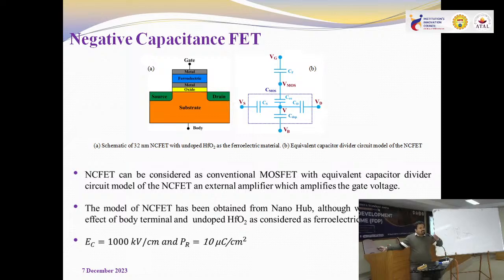No. TFE is there, meaning no ferroelectric is there. Then two metals are there. It's a MOSFET only. So whenever TFE equals 0 comes, we are discussing a simple MOSFET. I hope you understood what I'm trying to explain. When TFE equals 0, nothing is there, it's a MOSFET only. Whenever some ferroelectric thickness is there, we can call it an NCFET.